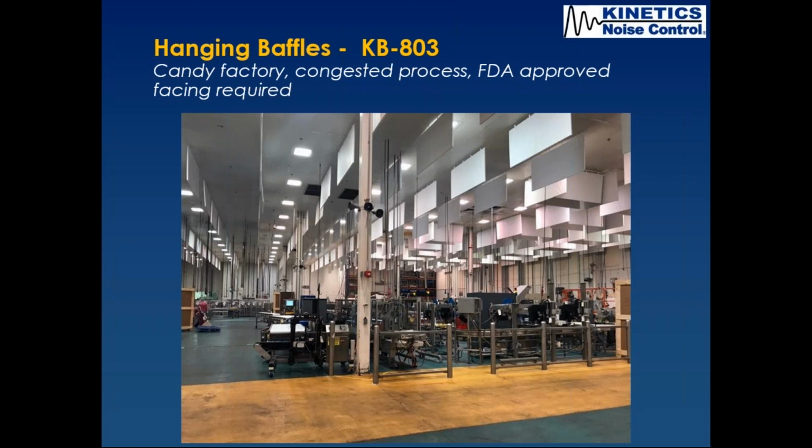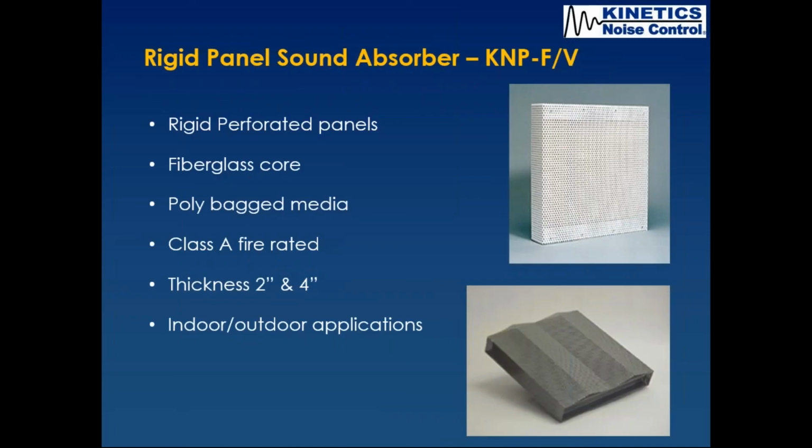And basically, as it's hung there, you're adding absorption to that space. It doesn't always matter where you put the absorption. All that matters is that you put it in the space. And these were actually with the Tyvek FDA approved facing, since it was a candy operation.